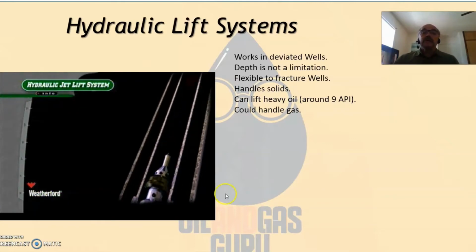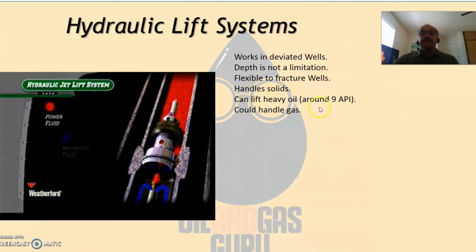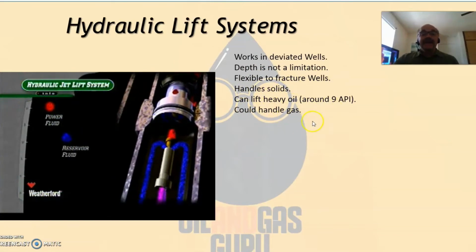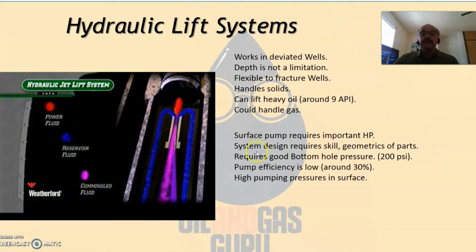So it works okay in deviated wells. Depth is not a limitation. Very flexible to fracture wells. Handles solids, heavy oil, and gas. But it requires high HP at surface.